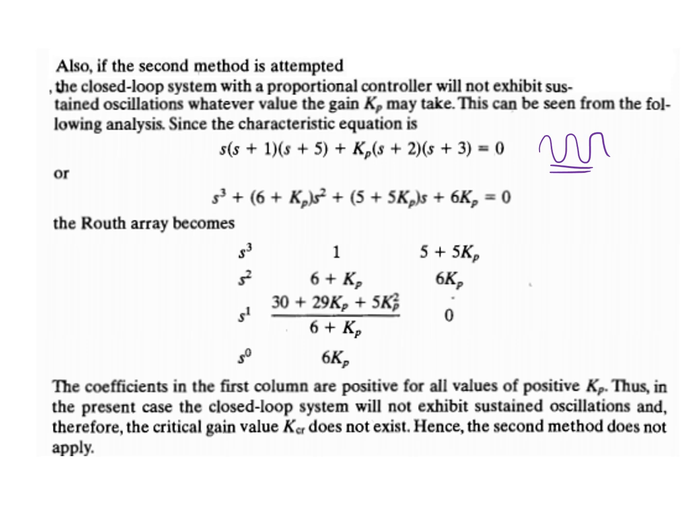In control systems, we have studied the Routh array. For example, this is the S plane. Here the curve starts like this and it settles. On this side, the left hand side produces like this, the right hand side produces like this. But on the imaginary axis, it produces sustained oscillation. So we have to check for which value the response stays on the imaginary axis. So we have to find out the sustained oscillations using the Routh array.